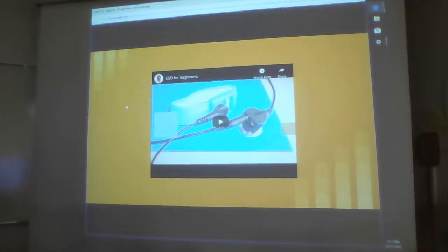Disney works with a lot of electrical components, as you can imagine, with all of their animatronic stuff and all the animatronic stuff that's in the roller coasters. So all toolboxes that had electrical tools had these ESD mats on top of them, and you're supposed to wear this bracelet. It grounds you to the mat, and the mat doesn't allow for any transfer of electrostatic discharge between, say, the toolbox and that component, or your tools and that component, stuff like that.